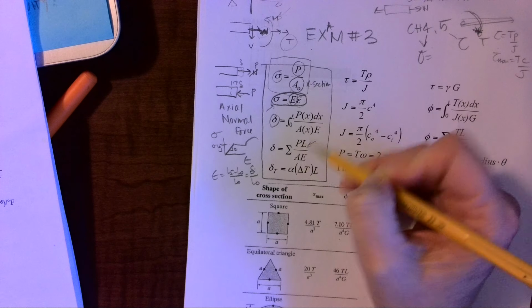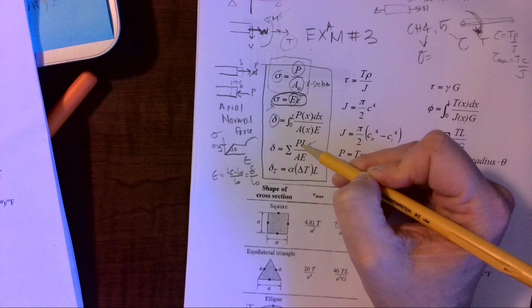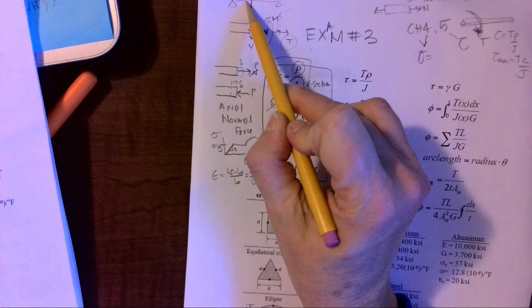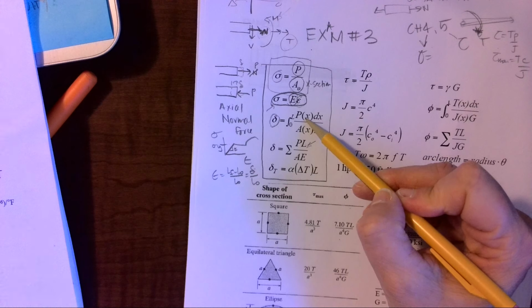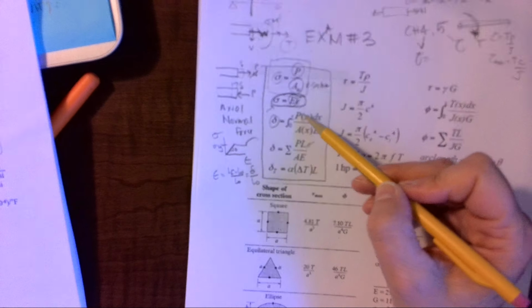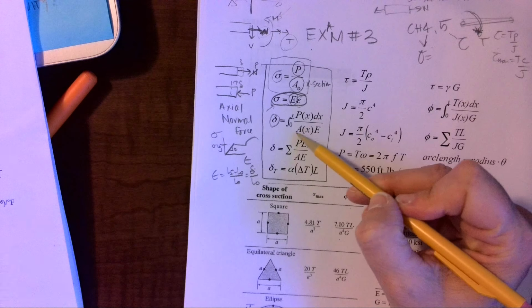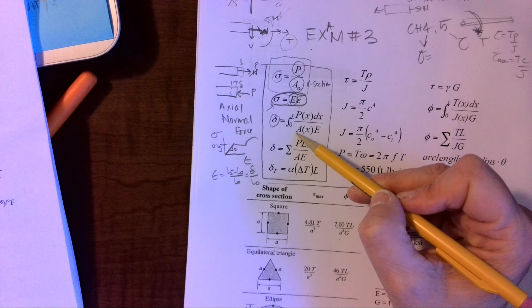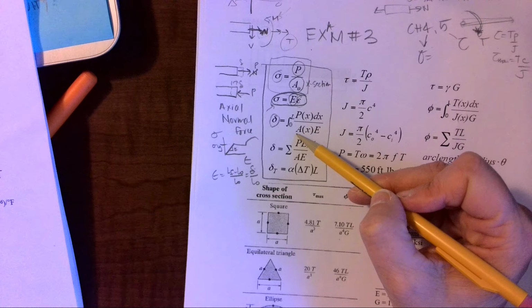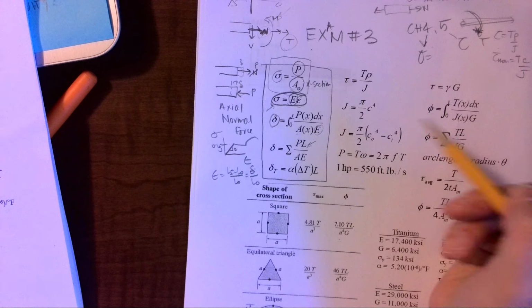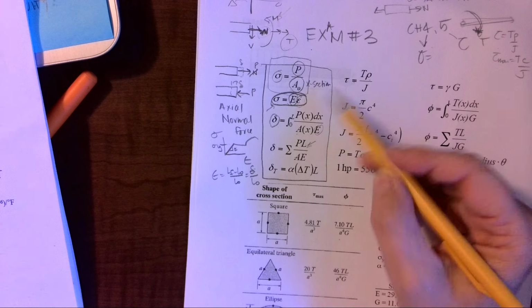This is where we have a very specific force through the segment. This would be if we have a variable force, so maybe it's increasing along the length, or we have a variable area, maybe it is being reduced in area, like looking like an ice cream cone, as we go through. E, we have one material, so that's the difference in these two.